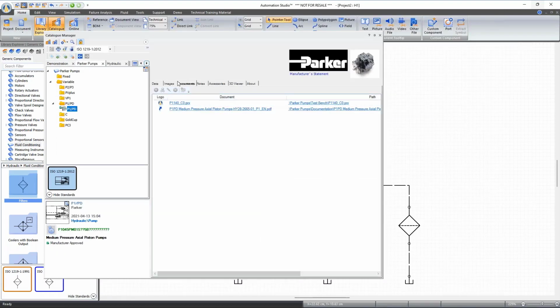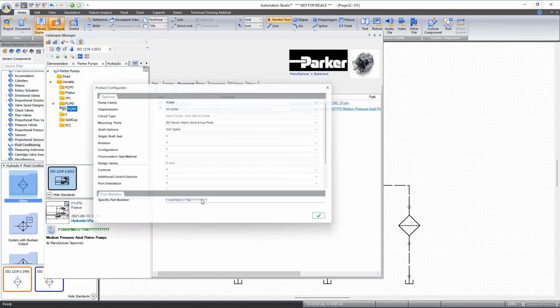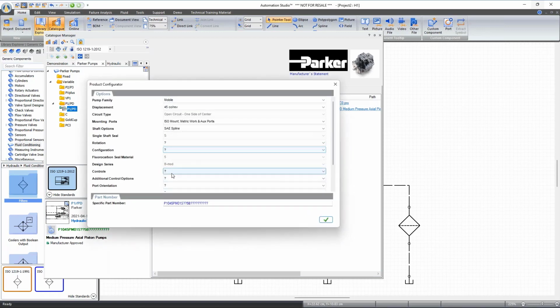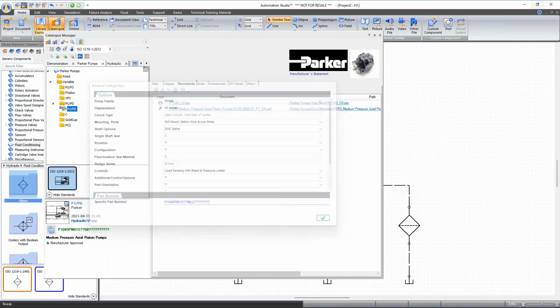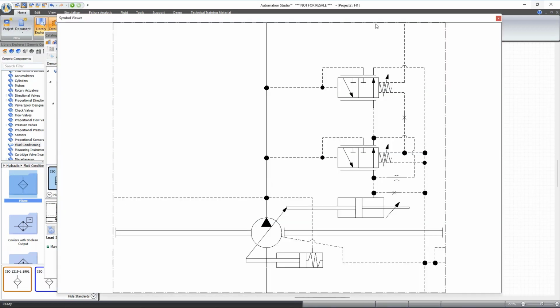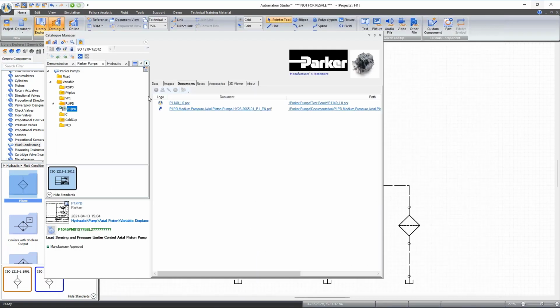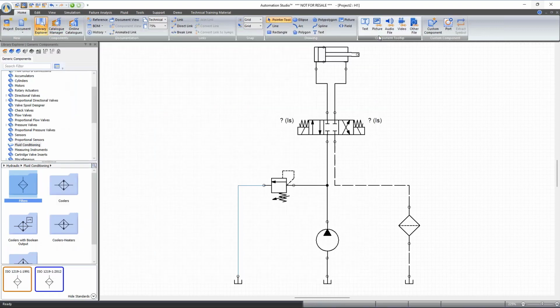And also, in the document tab that you have here, as you may know already, we do propose a test bench for each of the components we have in our catalogs, and the test bench will change as you change. Let me try to have a load sense control instead of what we see. The symbol has changed, and there is another PRX here. Instead of being C1, it's a C0, it's an L0, which will make sure that the test will test this configuration of that specific component.